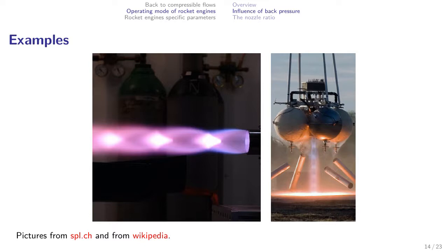When you see this kind of picture, you can be absolutely sure that the outlet pressure here is really higher than the ambient one. And from a propulsion efficiency standpoint, it's not the best solution.